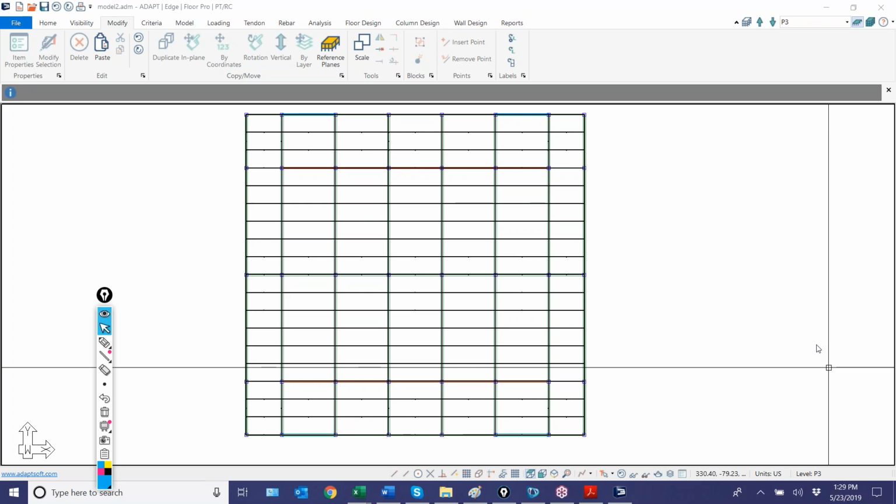One nice thing I'll say is we do plan on taking the crack deflection result, saving it as a usage case, and then having the ability to reapply the loss of stiffness, basically I effective, to a new run. That would completely eliminate what I just outlined for you, where after you run crack deflection, we automatically store those values, and then the user could reapply them as a modifier to every component that we check for, the slabs and the beams.